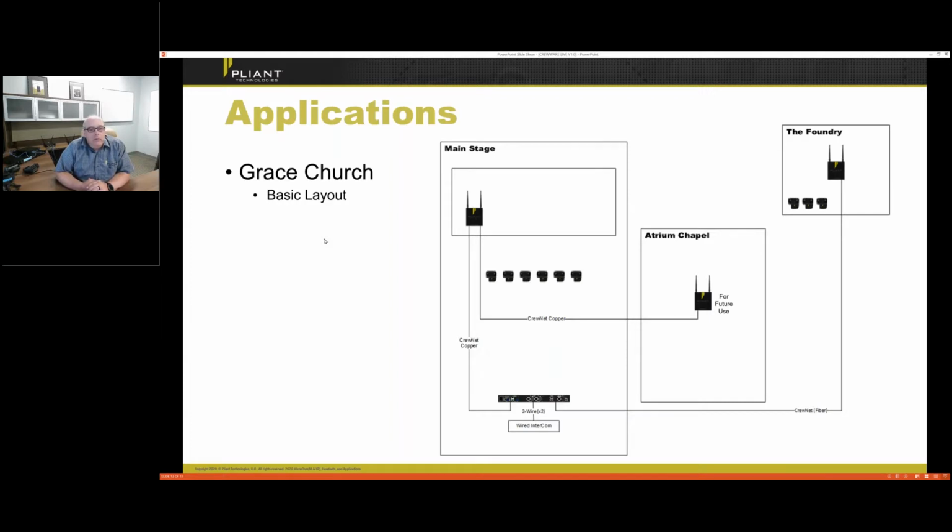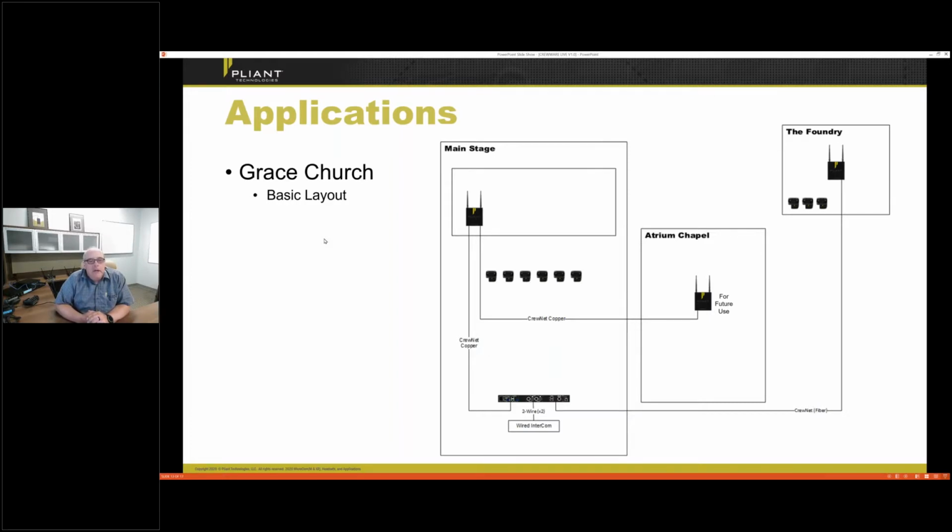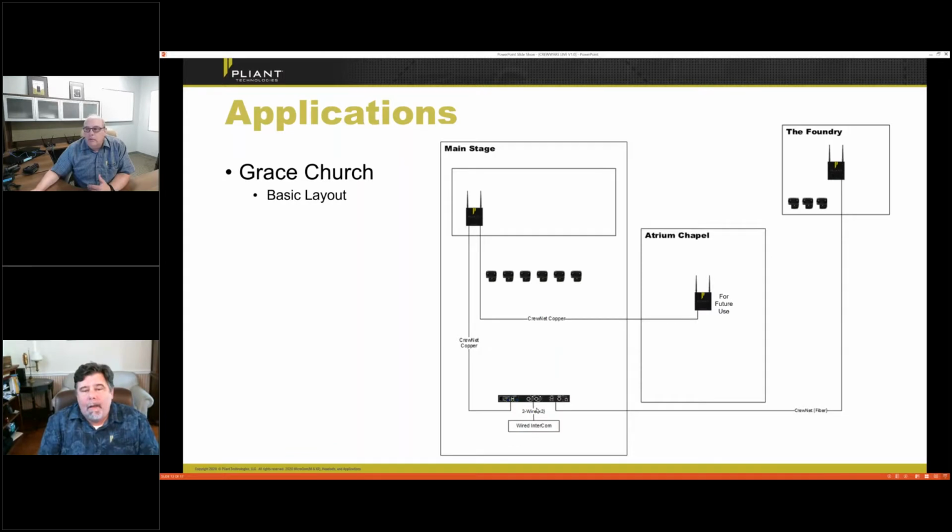You can save some money and also make the user experience more streamlined and easier in the example of a 2-knob belt pack being used. Yeah, actually, Mark, that's a great point. So, for instance, these guys, if they wanted to add a couple of 4 volume packs, you just add that, pair those to the system. Even though they're using a 2+2 control unit, you can have 4 volume packs on there. There could be 2 wireless, as long as you build a profile that supports a 4-knob 900 belt pack. Right. Because the profile is the heart of the whole thing. That's right. The power of the profile.